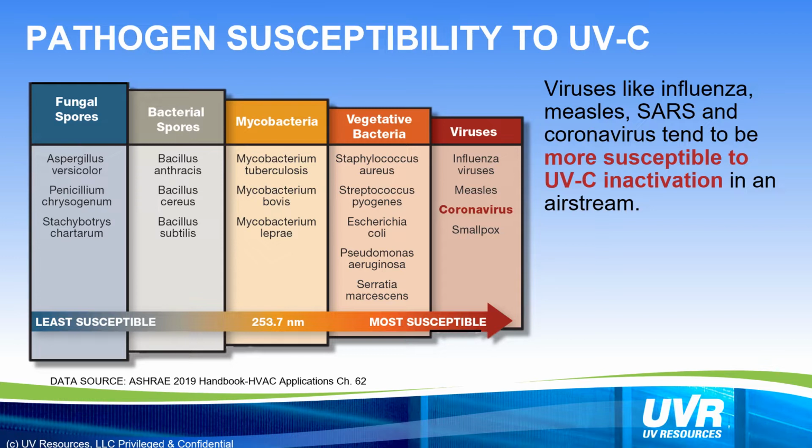Alternatively, fungal and bacterial spores, larger than 1 micron, are also susceptible to UVC. Because of their relatively larger size, spores take longer to inactivate, or a higher dose of UV is needed. Remember that these microorganisms are not typically flying by in the air, but growing in the dark, moisture-rich areas like coils and drain pans. These areas are treated as a surface UV application where we don't need a ton of UV energy since we have an infinite amount of time and length of exposure.